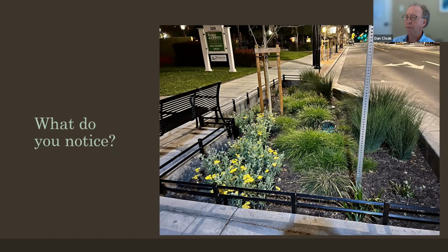There are a couple of things that I think sort of intuited out of that experience. One is that trees can totally get going in bioretention soil media. The direction on them is to make sure you stake them properly, as this one is, because obviously that soil media has no structural glue to it. It will just pull up, so trees can tip over. So they need to be staked.